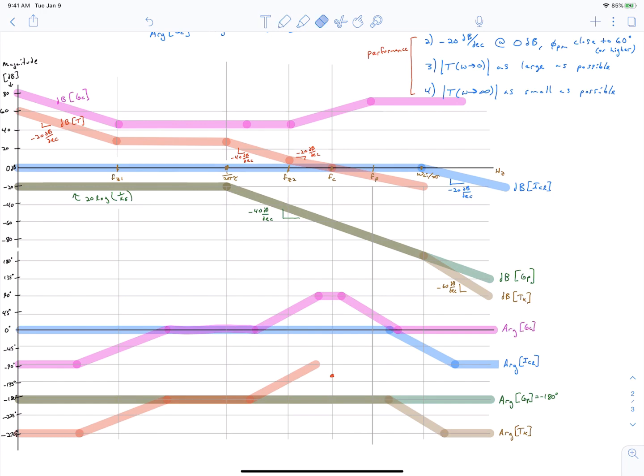And I'm going to draw this a little bit differently. Depending on where you place this, of course everything shifts around a bit, but realistically it probably occurs somewhere here. So we never actually get to a negative 90 degree phase margin in a typical situation. Let me adjust this a little bit more. What I'm trying to show is that your phase angle for your controller never actually gets to 90 degrees because, at least in the example as I'm drawing it, your pole kicks in before your zero's phase angle has completely reached 90 degrees. So we start rising up here, and we'd be continuing all the way to 90 degrees, but this pole is close enough that we instead level off at something like 60 degrees, and then start going down to 0 degrees.